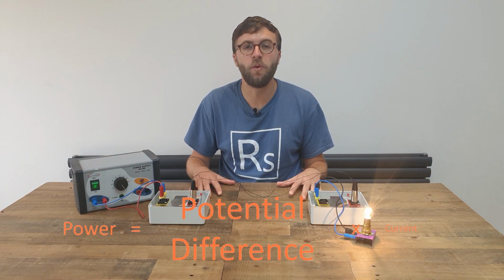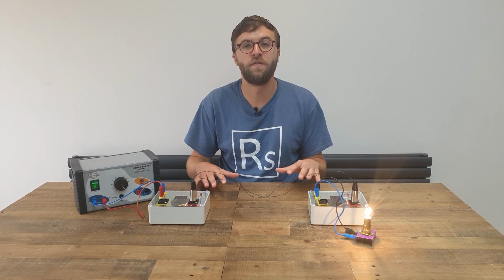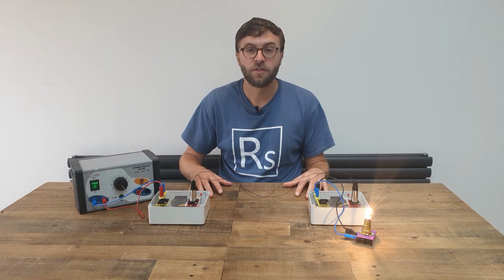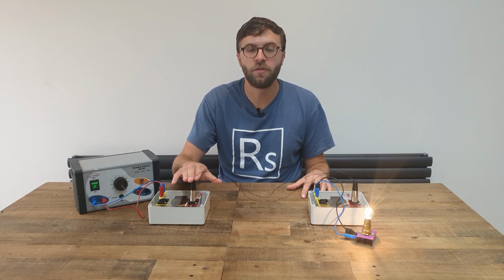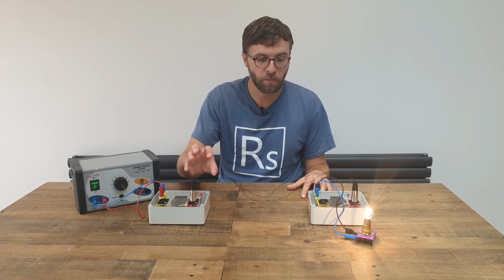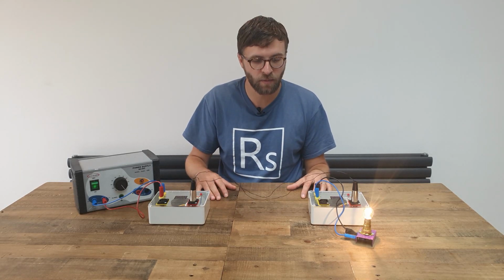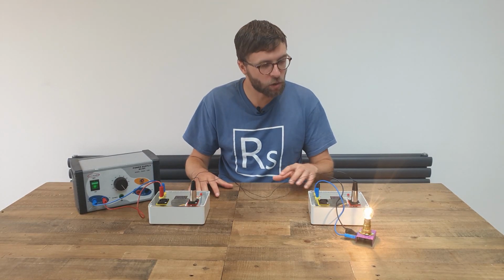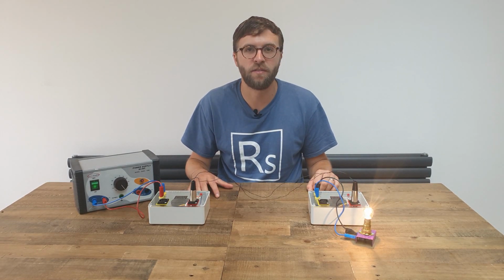If the current is smaller, then less energy is transferred to the surroundings, which makes the system much more efficient. So therefore, by having a high potential difference, we're transferring the energy more efficiently, losing less to the surroundings and getting more to the consumer. This is especially important over the long distances that the power has to travel.